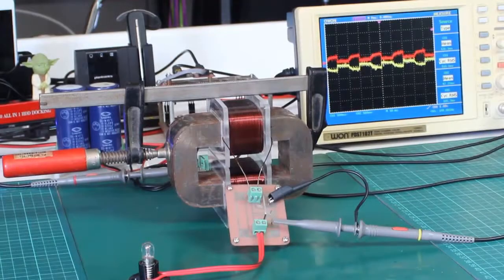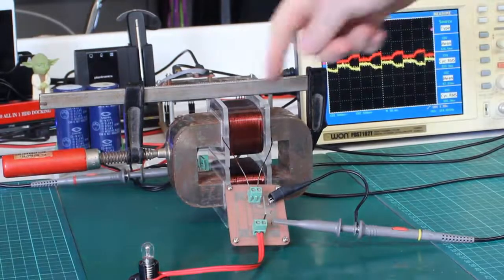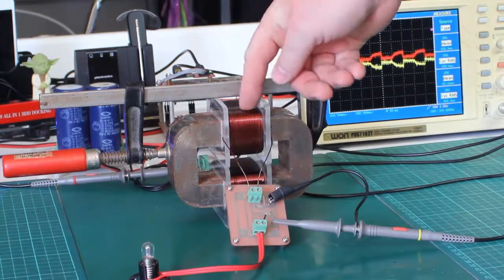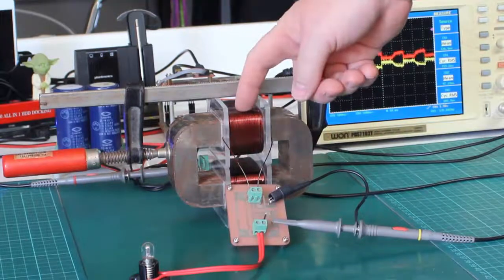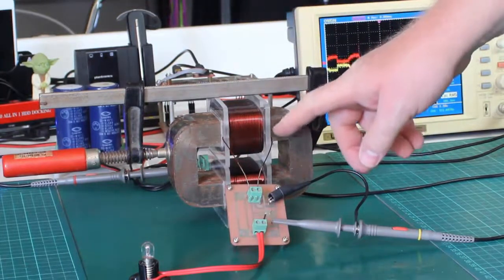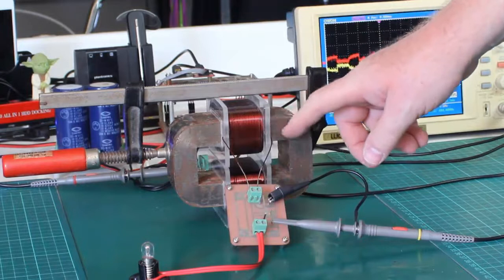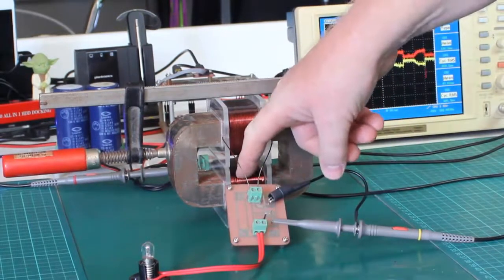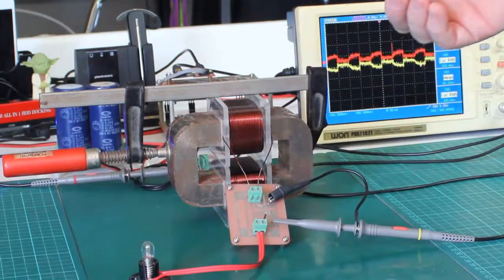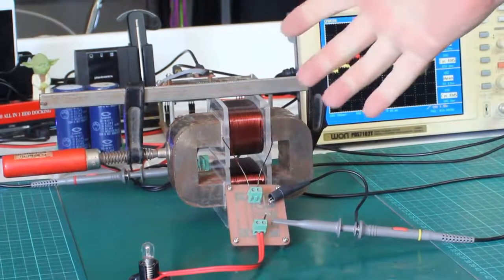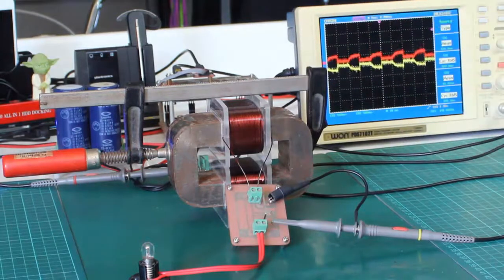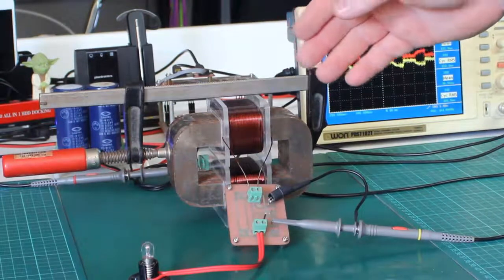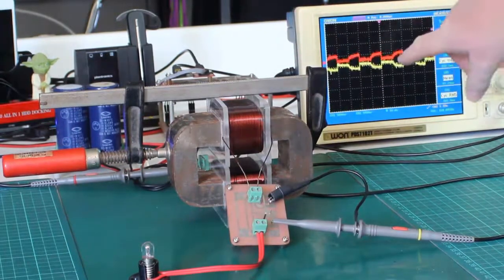So you can see that the turns here is a lot. I think from memory, it's about 250 turns each coil. So the top and the bottom are the same. Now, what we talked about before, again, is the propagation delay around the core. So the bottom coil down here is our input coil, and we give that input coil a big jolt of current. So we instantly switch in the voltage, and then the current rushes into the coil as fast as it can, and that's the curve.